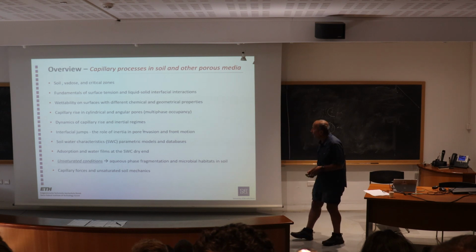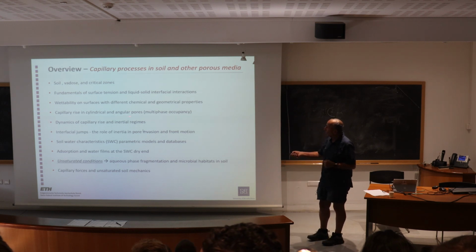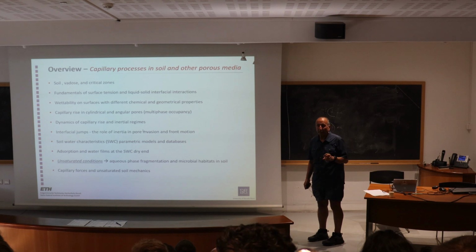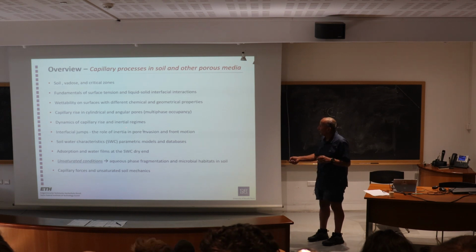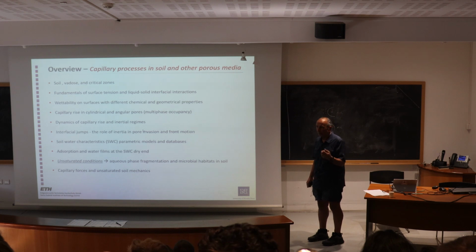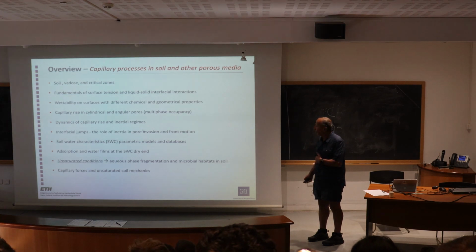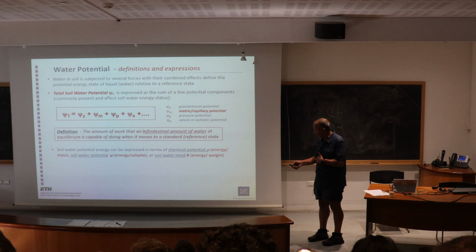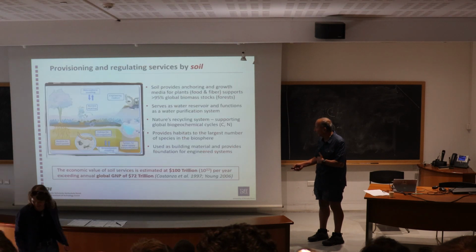I'll focus on soil. We'll talk about wettability, capillary rise in cylindrical and angular pores, dynamics of capillary rise, interfacial jumps, stuff that happens at drainage and wetting fronts. That will be interesting because yesterday we heard a little bit about inertia, and today I'll try to hammer that a little bit more.